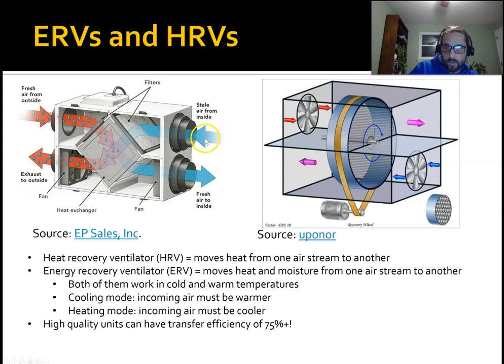So this cold air, which we want to keep cool, instead of just ejecting it outside, we basically warm it up. We pull some heat from that incoming air and reject it outside, and then the air that comes in that was hot and humid actually cools down and is a little dehumidified. So it actually comes in cooler than it would otherwise. That's the principle of an ERV.